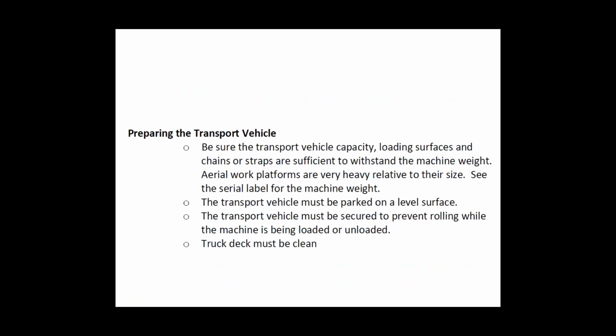So now that we're preparing the vehicle for transport, we need to be sure, again, that the loading surfaces aren't slippery or have oil on them. We need to make sure that we have the right rigging hardware for the machine that we're carrying. So again, we need to be cognizant of the weight of the machine that we're transporting.